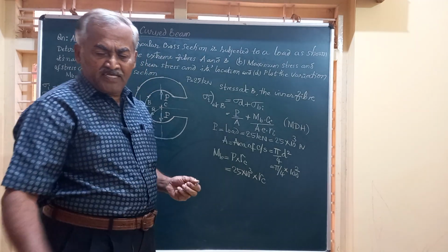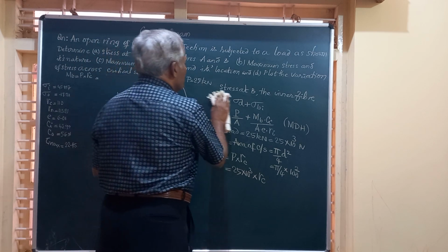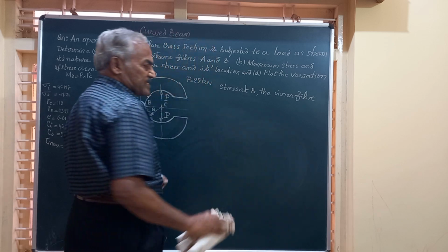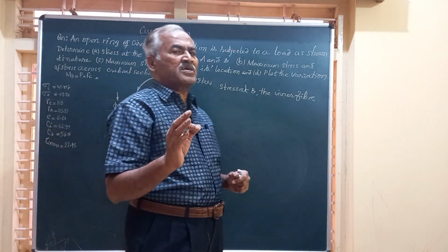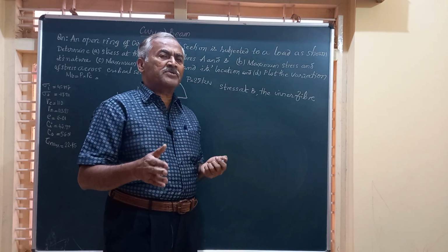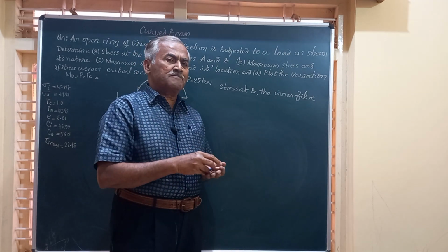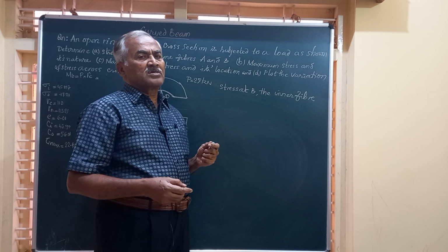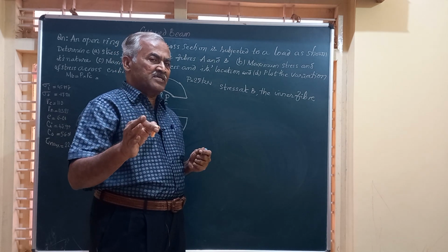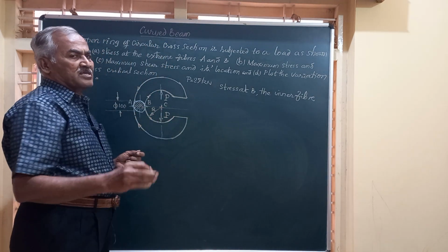So friends, in the second step, after getting this information, we will find out what are these values of RC, etc. Friends, please remember in this chapter, the second step, what I am going to tell you is very, very important because the cross section of this curved beam could be trapezoidal, which is very common, or I section, or T section, or rectangular section, along with this circular cross section.